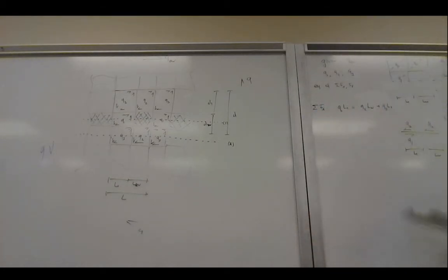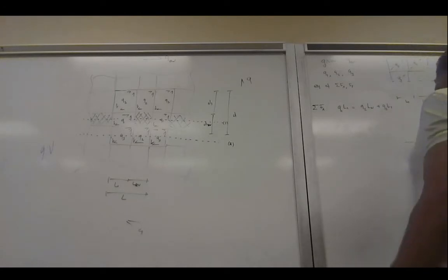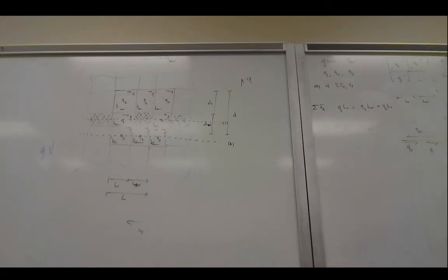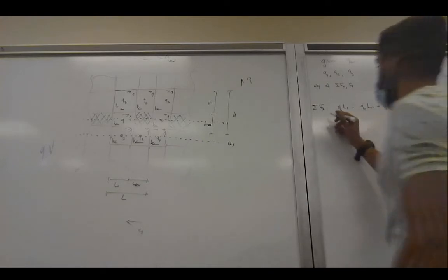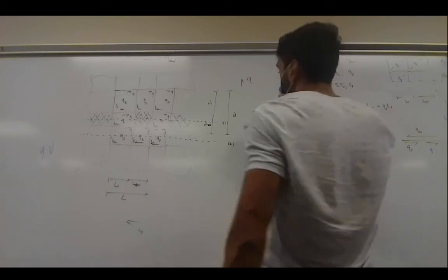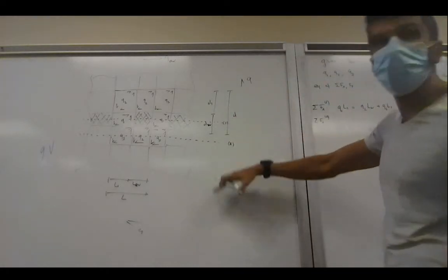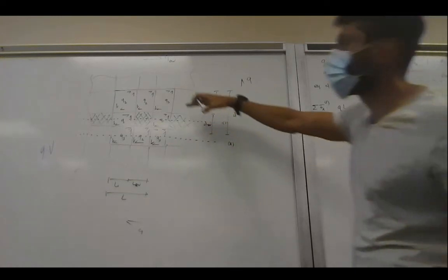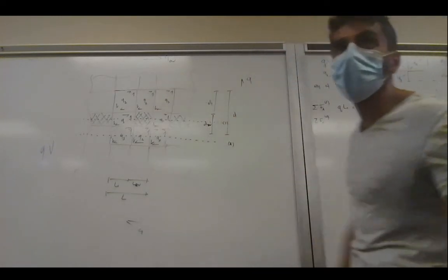And you can repeat the same thing on the top side, where you basically have Q3, Q2, and this is the segment, and on the top side you have the average shear flow, which was the far field shear flow. And you can repeat the same thing. So we now did the equation at location 1, basically summation of forces, and then we do the summation of forces at location 2, somewhere far away from our cutout, say at the segment where we have our average shear flow again.